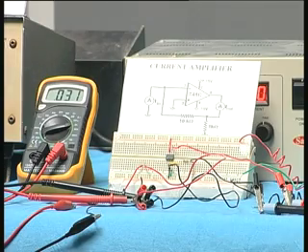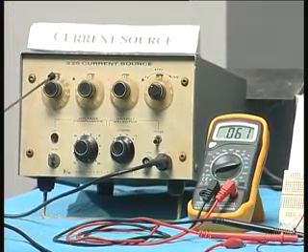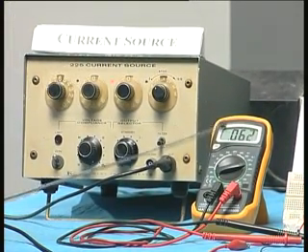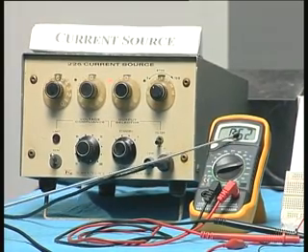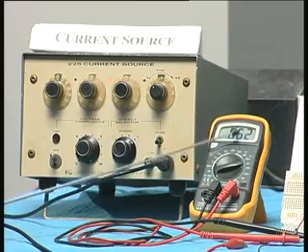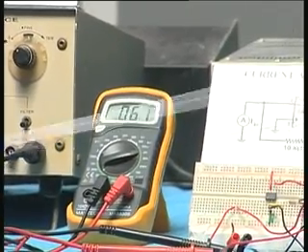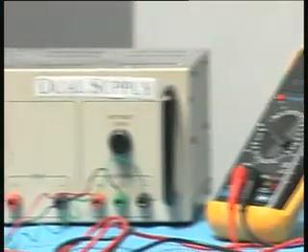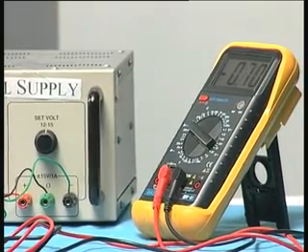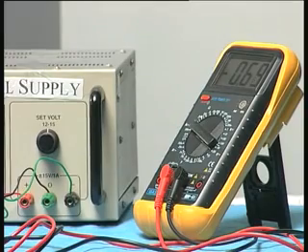Now, last time, I will try some additional value. For example, I have now put 60 microamperes, as you can see here, 0.062. So this is 62 or 63 microamperes, that is what it reads here, multiplied by 11 should be around 66 or so, and you can see the output is around 69 or 68. So you can see the output current is multiplied by 1 plus R2 by R1, which is the gain factor here.